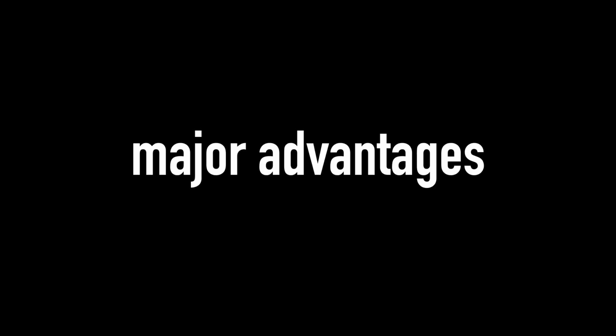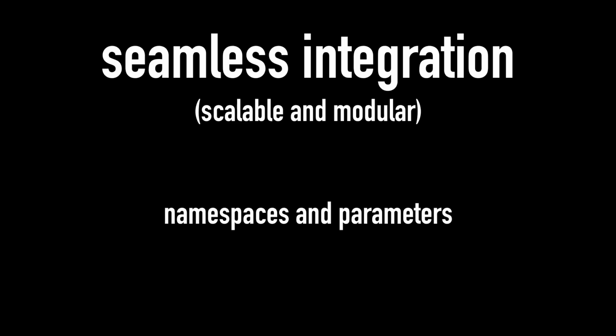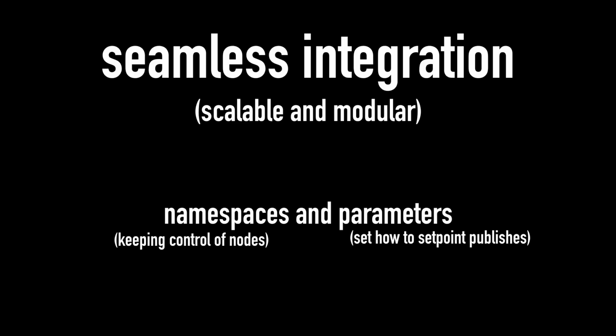Of course, every system has its strengths and weaknesses. One of the major advantages of our approach was the seamless integration with ROS2, making it highly scalable and modular. This means future improvements such as adding more advanced controllers or additional sensors can be incorporated without redesigning the entire system, which, by the way, was way easier for us since we involved the use of namespaces and parameters for the setpoint node. However, there were some challenges too.